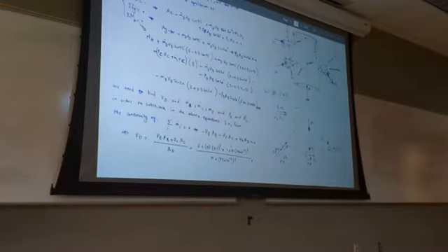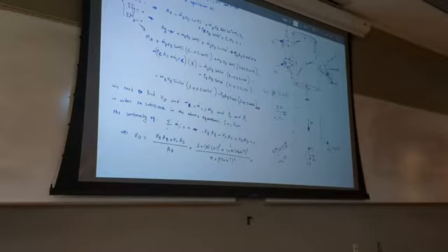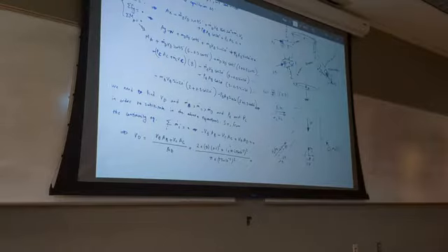So the way of doing the Bernoulli equation, we started with momentum. So we had this equation, partial t of integral rho V dV, plus surface integral rho V (V dot n) dS is equal to the sum of F external. So we started with that, and then next step, we made an assumption, no shear stress.